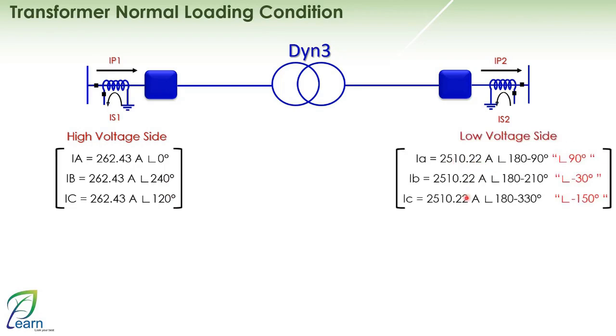And regarding the angle, let's see together the angle. Now, you have the current here. It went out from one point and went to point D and therefore, for me, it will be an angle of 0 degrees with respect to the angle of minus 120 for the yellow phase and an angle of 120 for the blue phase. Okay? Towards the low voltage side, what is the situation for me? The idea is quite simple, as we see, that the current here is reversed, meaning it went out from the dot point, so it approximates an angle of 180 degrees.